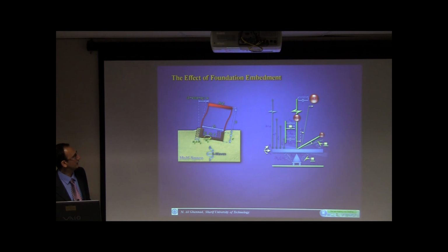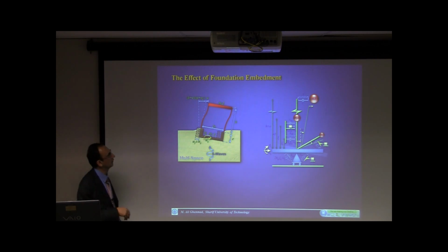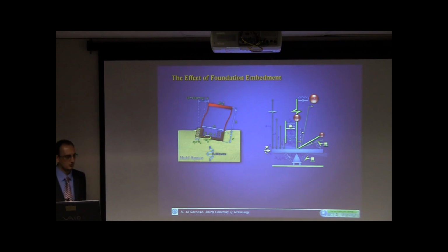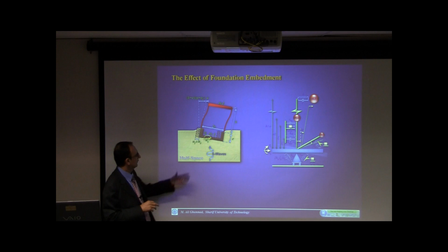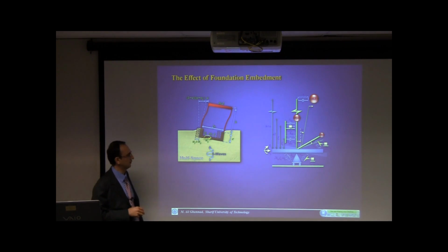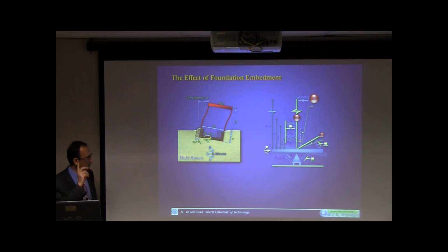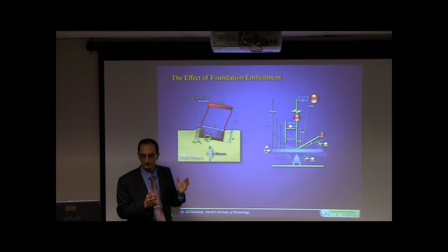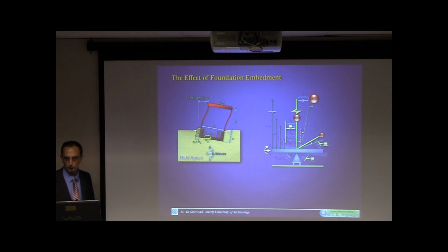I go very briefly to the foundation. Actually, I was thinking to talk about the foundation embedment, because the embedment is a long story, of course. It's very complicated. When you go to embedded foundations, you have to take care of the nonlinearity in the soil, the local nonlinearity, the separation of the foundation and the soil, of course.